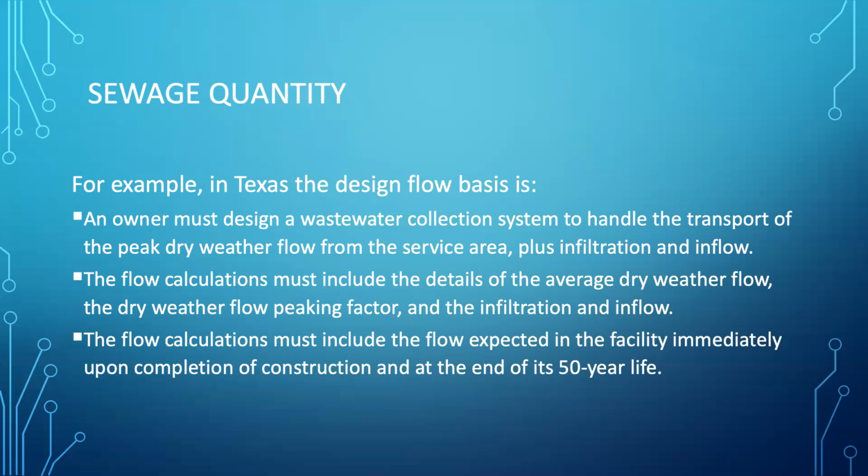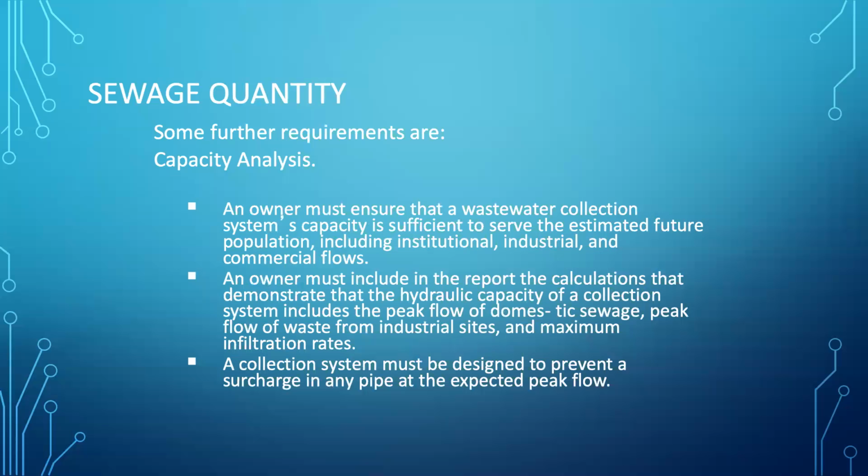And we'll get to what infiltration and inflow are shortly. The flow calculations must include the details of the average dry weather flow, the dry weather flow peaking factor, and the infiltration and inflow. And there's tables to provide some of those answers. And it includes the flow expected at completion and at the end of its 50-year service life.